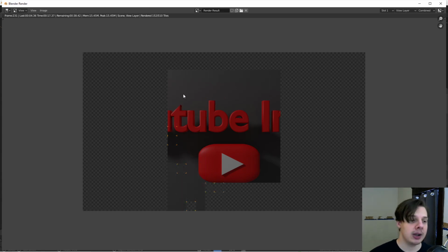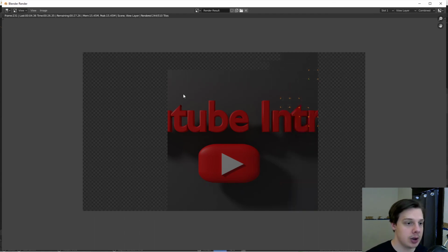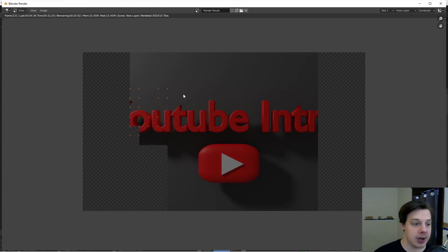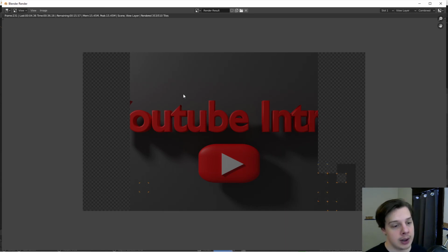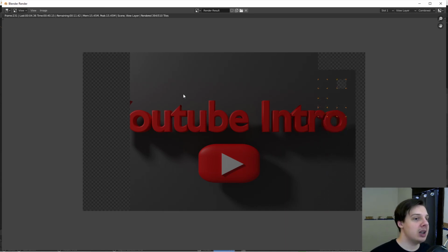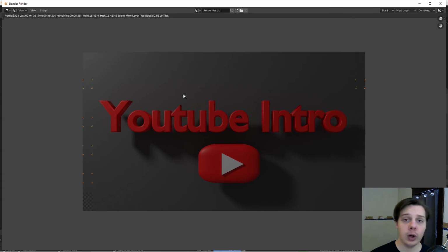Not too bad. You can cut down on that by changing post-processing effects. Some of the ways it renders, you can maybe make it so there's less resolution on the bevels, less segments on the bevels for the square. You can do quite a lot to decrease the render time, but mainly you want to take however long it takes to render an image and multiply that by 250, or however many frames are in your animation.